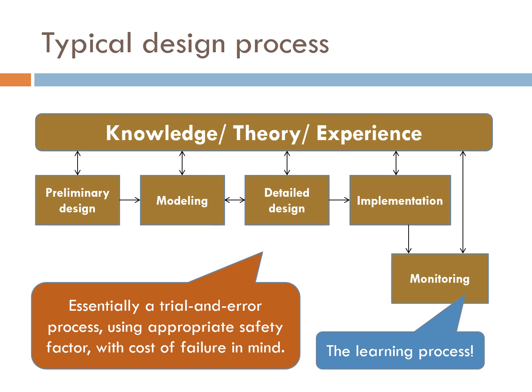So essentially, the entire process of coastal design is a trial and error process, because every coastline is different and every coastline is subjected to different coastal climate and localized processes. And so the use of an appropriate safety factor and also cost consciousness is highly important in order to make sure that a good solution is provided.